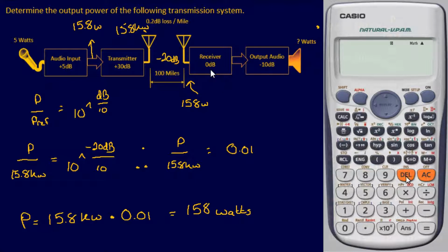All right. Well, from here to here, there seems to be a 0 decibel change. Anytime there's a 0 decibel change, there's no point in actually going through this calculation, because anytime you have a 0 decibel over 10, it's going to be 0. When you have an anti-log of 0, it's actually going to be 1. So this whole thing right here would equal 1 times your reference. So this guy right here is going to be the same as your input.